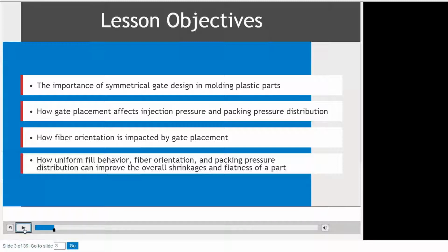Wall thickness distribution. Do we have ribs? All of this will impact the quality of the part. And that's why it's so important to understand the cause and effect behavior between the polymer material and the part design. That's number one. That's first. If we understand this behavior, if we can optimize the part design based on the material, only then we should go into the mold design.